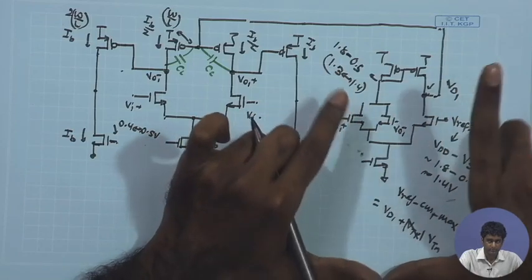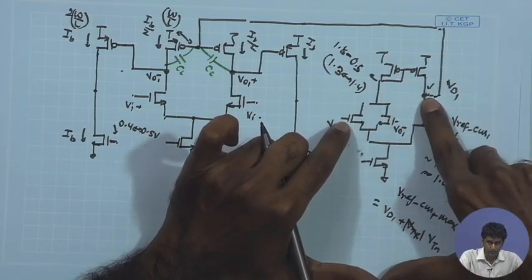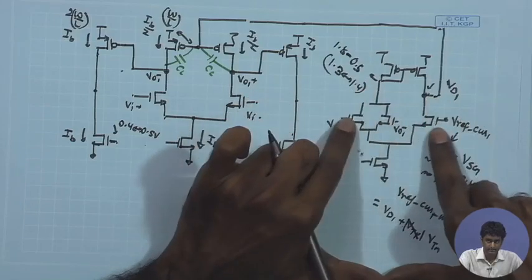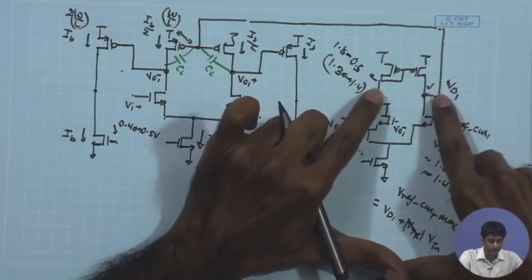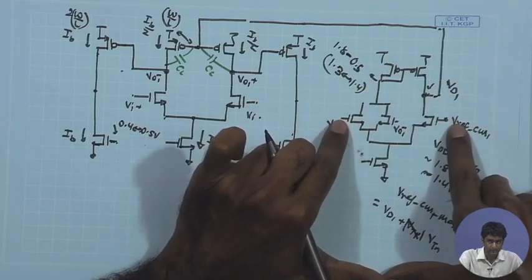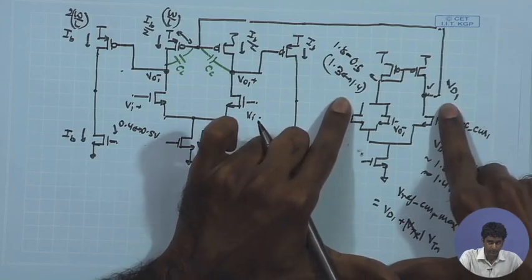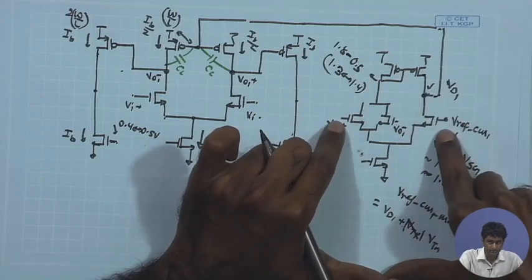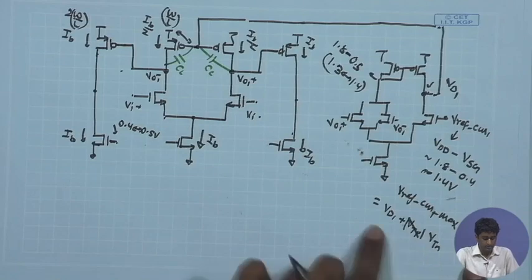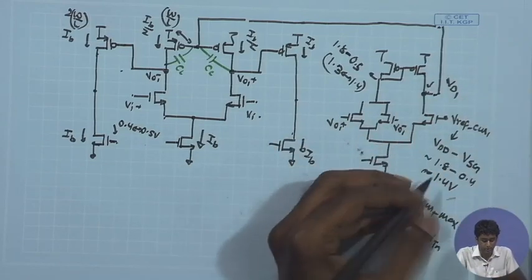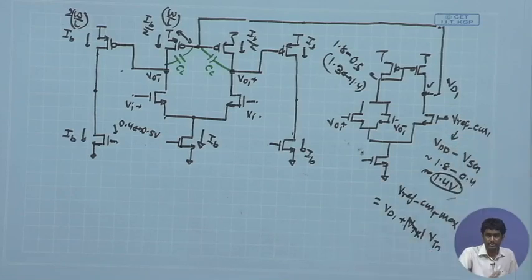So, that is why we are first of all finding out the Vd1, which is going to be close to the DC potential over here, as long as these two potentials are close, and then for that Vd1, the maximum VCM ref that you can have is going to be equal to Vd1 plus Vt. So, that is going to be pretty large, it can go very close to VDD. So, 1.4 is not an issue as a VCM ref.